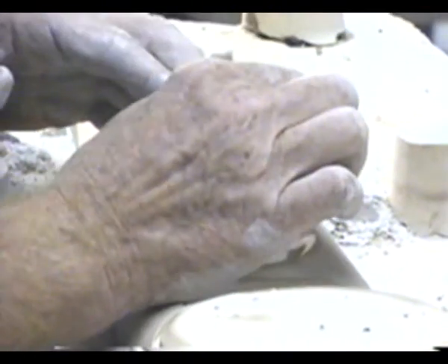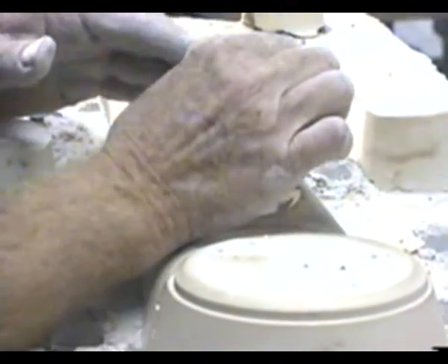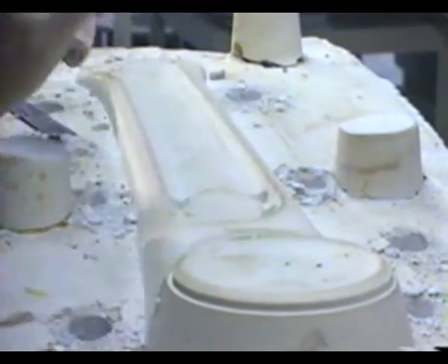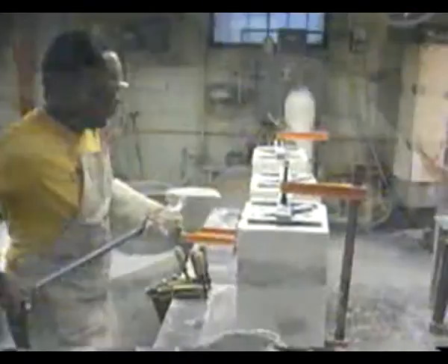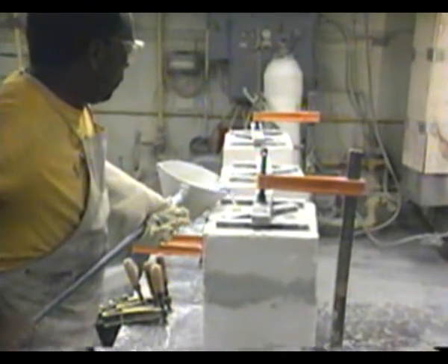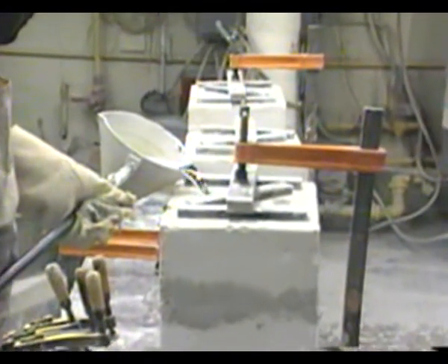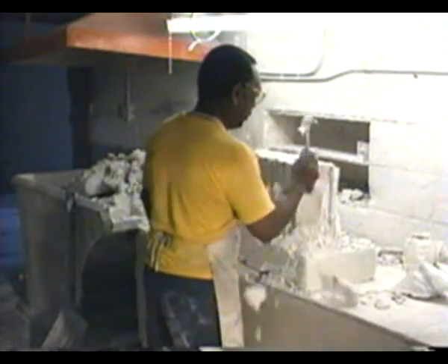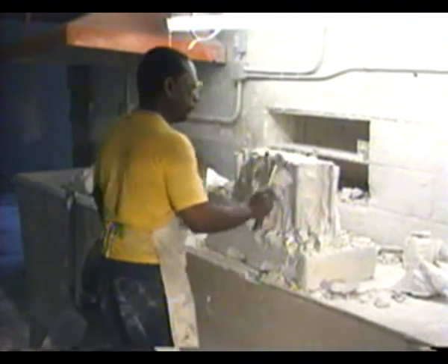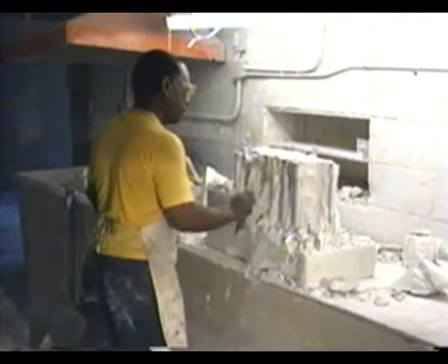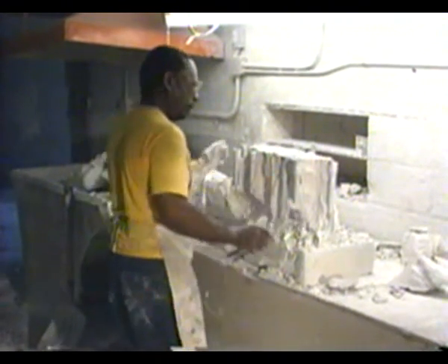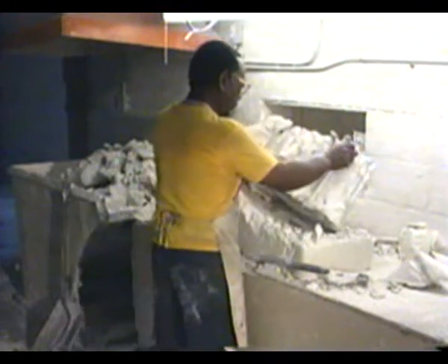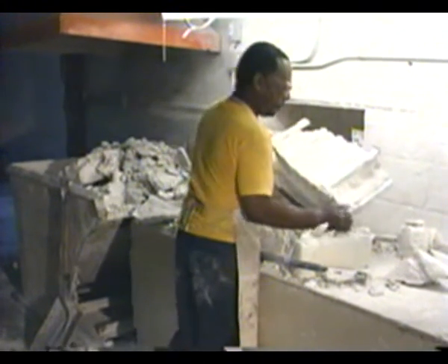The molds may incorporate metal inserts called chills to speed solidification and enhance the strength of the casting in local regions. Plaster molds have low thermal conductivity, so castings take longer to solidify than in sand molds. Plaster mold castings are typically small, less than 45 kilograms by weight, usually much less. But cast shapes can be extremely complex and have very thin sections.